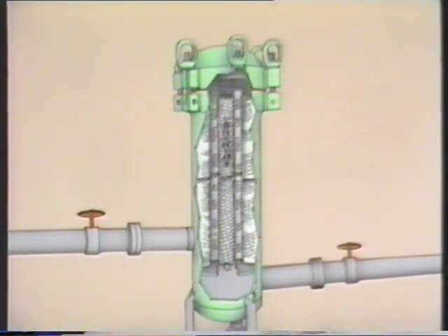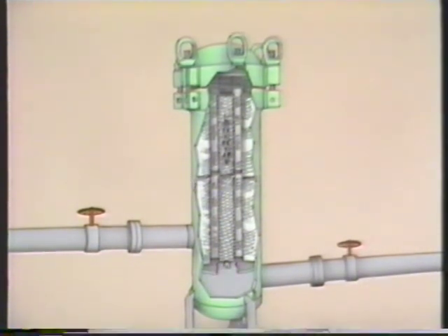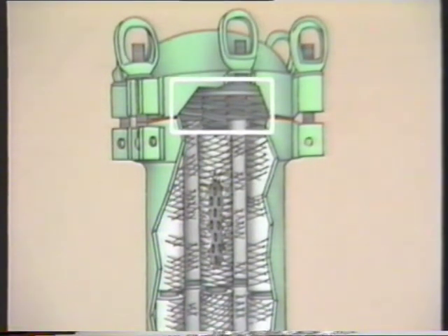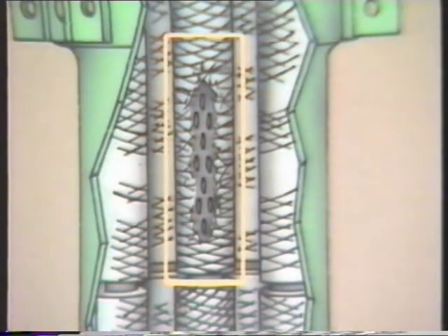This cartridge filter consists of seat plate assemblies, filter tubes connected by spacers, and tube guides. All of these parts fit inside the filter housing. This seat plate assembly seals one end of the center core and works with the tube guide to hold the filter tube in place inside the filter housing. Each filter tube has filter medium that surrounds a center core.